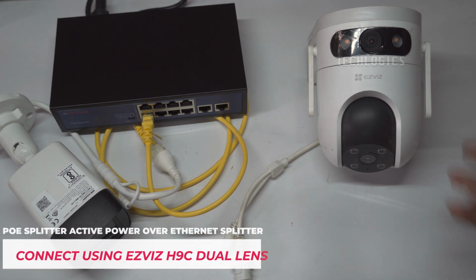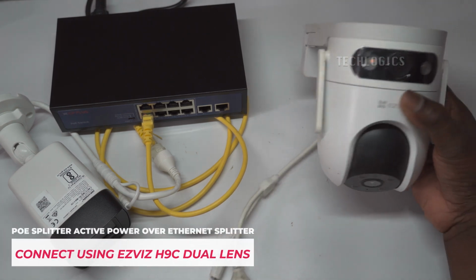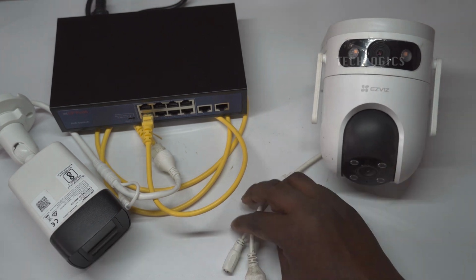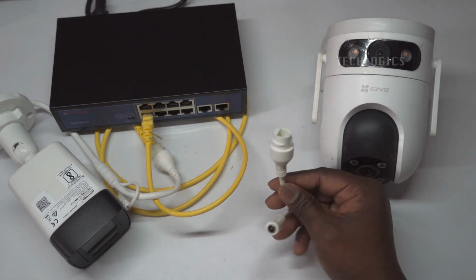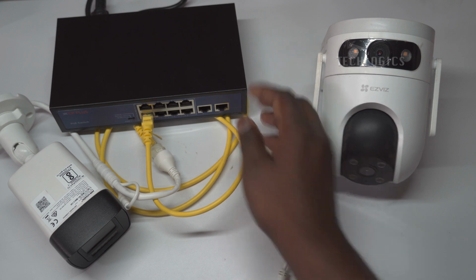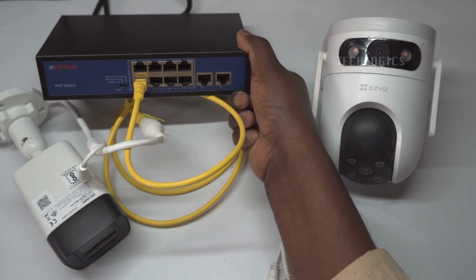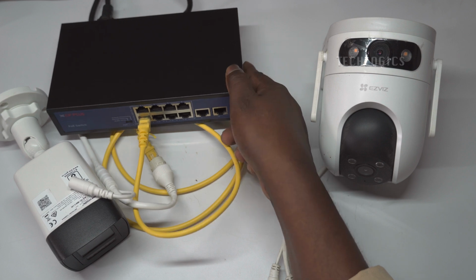Hello everyone. Today, we are using an active PoE splitter to connect the ESVIZ dual-lens Wi-Fi camera. Since the PoE switch does not directly support the PoE requirements of the ESVIZ H9C, the PoE splitter will convert the power and data from the switch to meet the camera's needs.